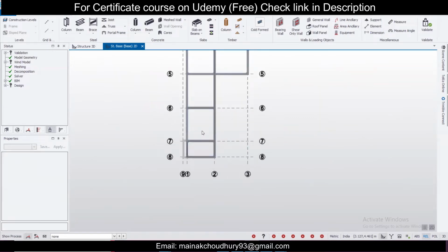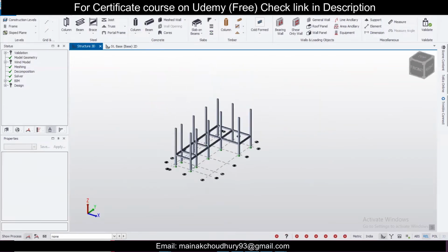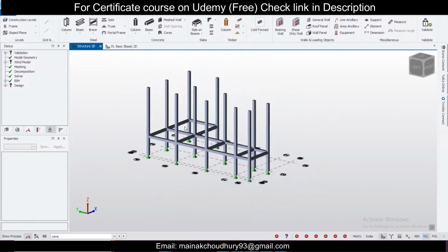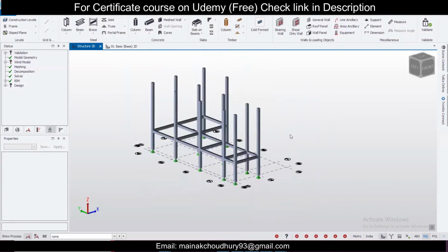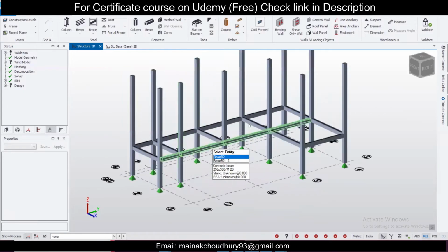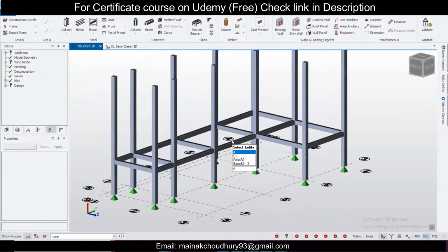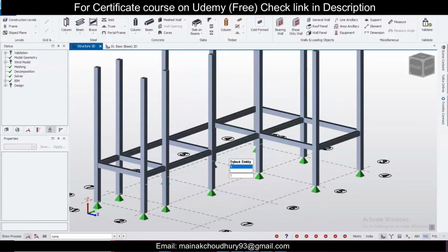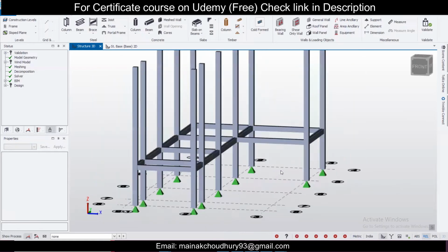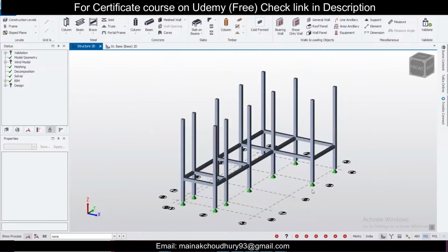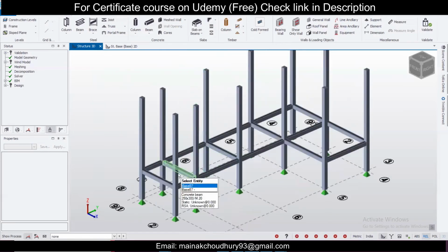Now once this is done, you can check the structure in 3D, and this is the plinth beam which is ready. Some people make a mistake with the plinth beam. It is the convention that they also put slabs here, but generally in a normal residential building, the sand filling is done after the PCC is done. So no need to put any slab here unless there is no compacted earth below. All the load goes to the compacted earth, so no need of providing this slab. I'm talking of any software like STAAD Pro, ETABS, any software. You don't need to provide any slab in the base here.